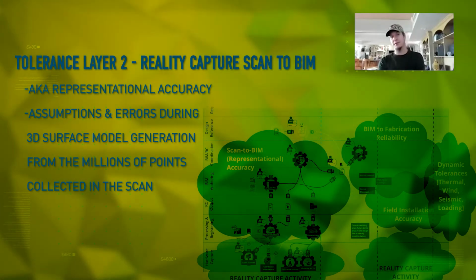And this is an area of hot debate, but there's a couple of different methodologies to register scans. There's traditional survey control, that doesn't technically have to be on some legally defined coordinate system, but just some kind of defined control network. There's targeting, which is similar in nature, but much denser, lots and lots of targets compared to just a couple of control points. And then, of course, there's cloud to cloud, which is all the rage and super popular. It's the quote unquote easy button of scanning registration, except when it fails miserably, in which case it becomes the pain in your ass button.